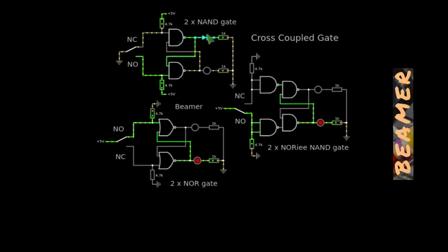The green LED, incidentally, is not really a green LED. In fact, in my application, this was actually a transistor-driven relay. And in fact, if my memory serves me correctly, the relay I used was a reed relay because the application only required a switch with 2 wires, which is in a normally open position, and when magnetized, the reed switch would close.